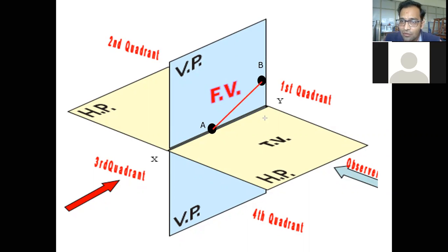So here, when I want to represent the line, I am having different aspects of observation. I have to trace it down for its observation in plan and elevation. I'm just drafting the positions now. Afterwards, we'll be indicating the numbers or data in numeric values so that we can represent it in proper way. I'm tracing it down over here on horizontal plane. Point A is traced down, point B is traced down. In similar manner, I'll be tracing it on vertical plane. Point A is traced down, point B is traced down.